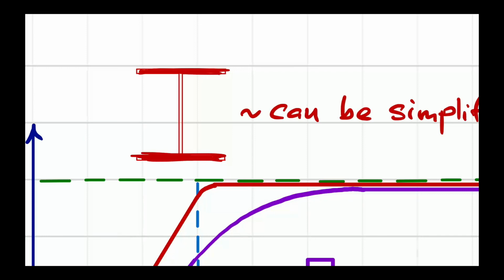And as the entire flange yields, the flange contributes pretty much the most to the capacity of the wide flange cross section. So you can see the first yield of this surface, and in a bit you have the complete flange thickness yielding.